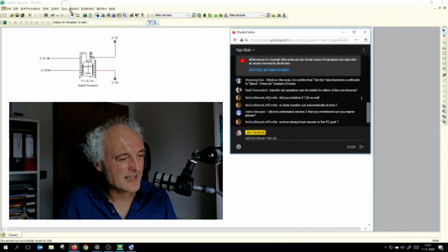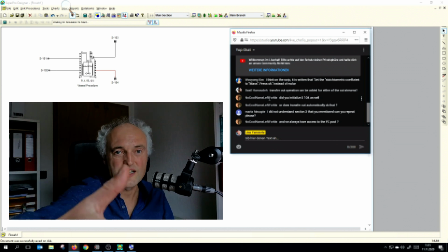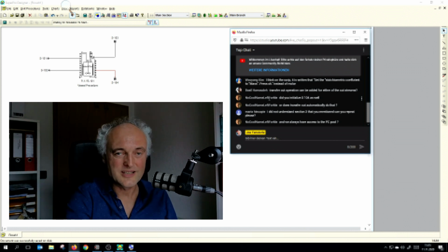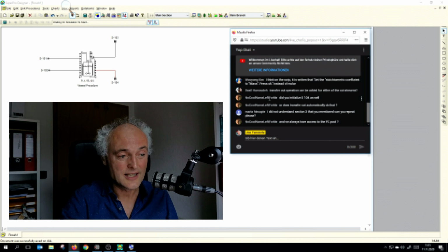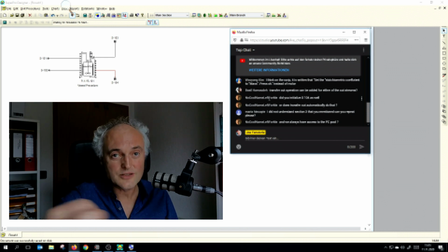Yeah, you don't initialize S104 because this is not something which you charge. You only need to initialize things which you charge. It's a transfer, so this comes from an upstream operation. It's good to check the help in this case also. So I don't need to initialize it because it's reacting, and then the only thing I need to do, for the transfer out, is this goes into the stream 104, and everything which comes out of the reactor is then